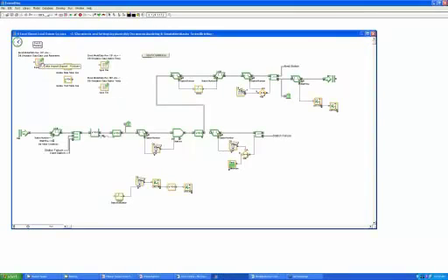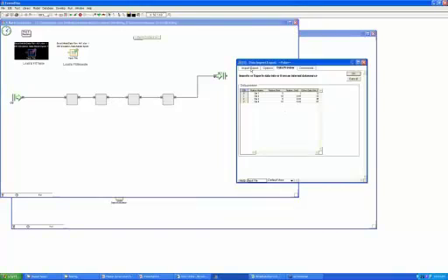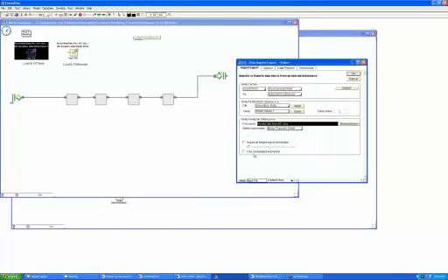One of the unique things about the data import export block, and I'll pull up the original ones. Inside the import export block there are a couple of check boxes. Import at the beginning of a simulation is set up for an import, and one of the unique things about this is import at the first run of multi-run only. This is a very important feature in 8. In R7, Dave and I went round and round on how to do this, and thankfully it's in 8.